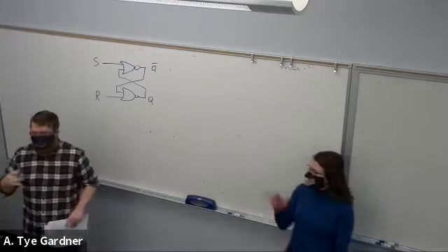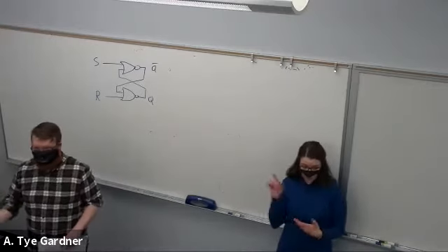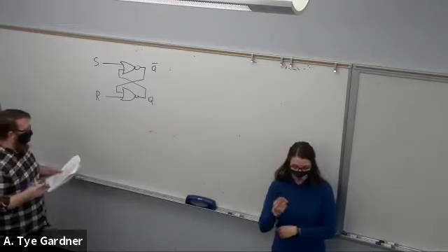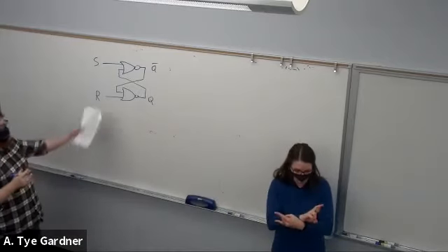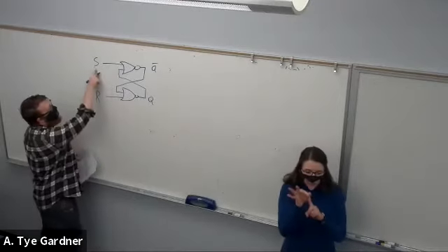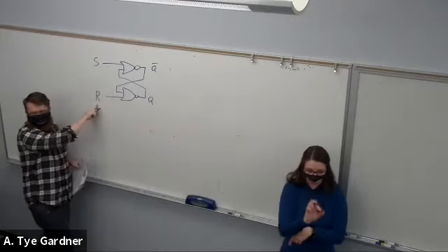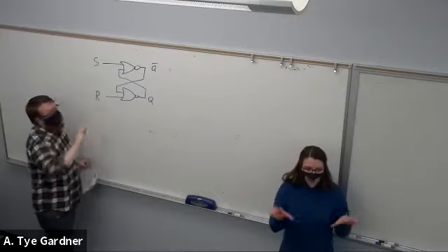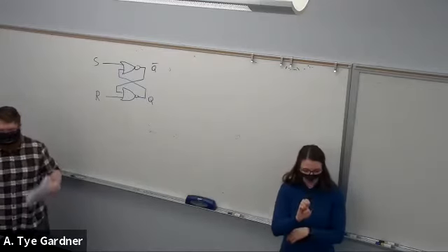Here we go. So this is an SR latch built off of NOR gates. The NAND gate looks virtually identical. The difference in the NAND gate implementation is the set and reset are active low. All right, so what is this circuit doing?